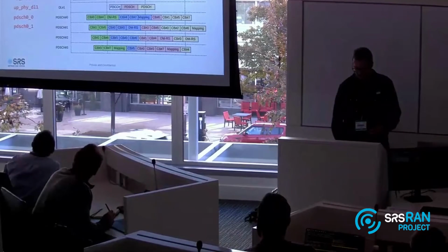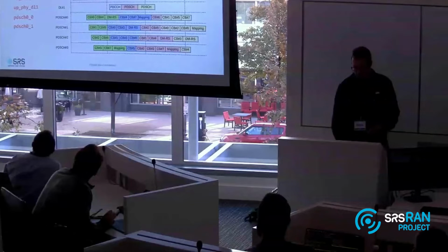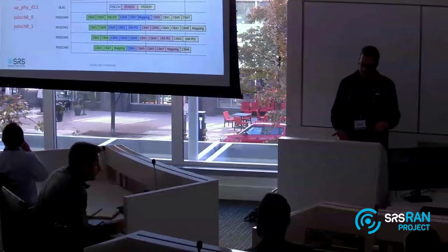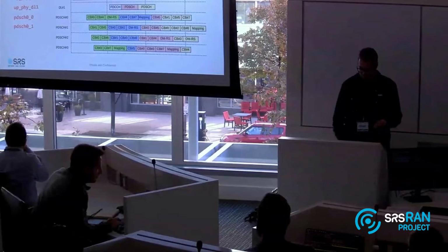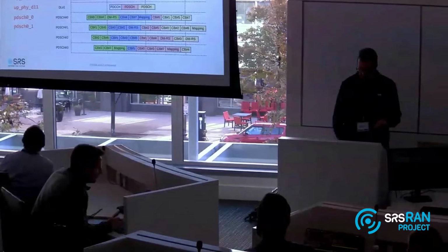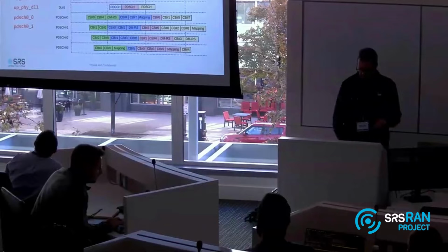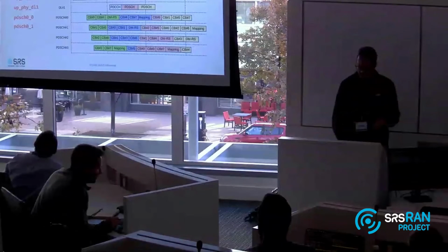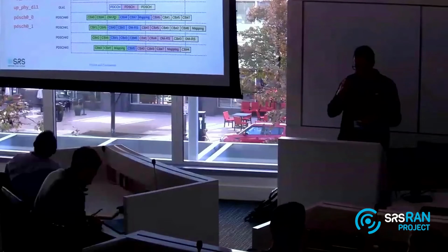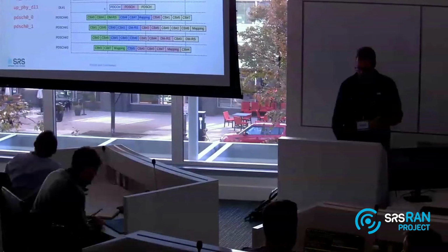When the transmit data request arrives, in this example, let's say that there are 2 users, and it needs to generate 2 transport blocks, 1 for each user. This transport block will be further divided into these tasks, 1 for each code block. Let's say that there are 8 code blocks. An extra task is the DMRS that is generated in a separate task.